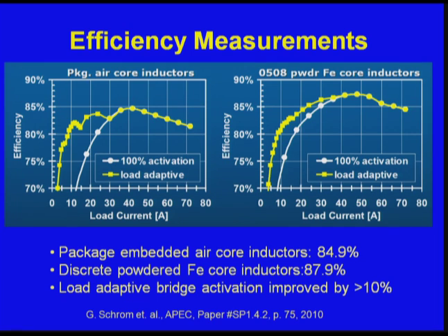Now, you'll probably remember that our earlier presenter had pointed out that one of the problems with buck converters, especially if you start going to multi-phase converters, this one is up to 16 phases, is that when you lower your load to very low currents, your efficiency starts to drop off a lot. So this particular design has adaptive techniques that help boost efficiency back up by cutting back on various parameters. Details of that study are published in the APEC paper that was presented last year.